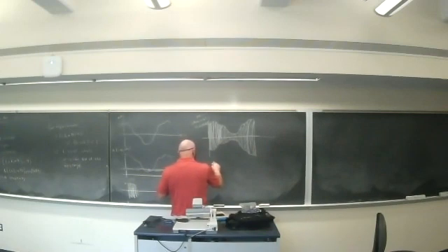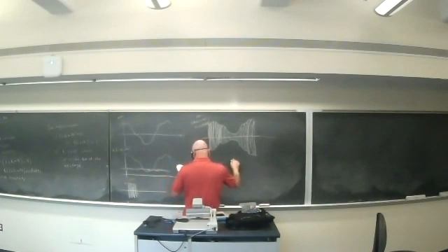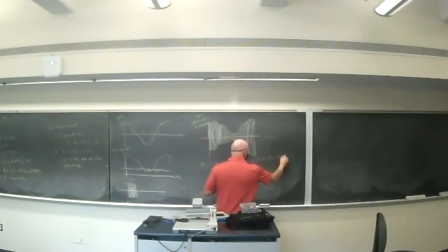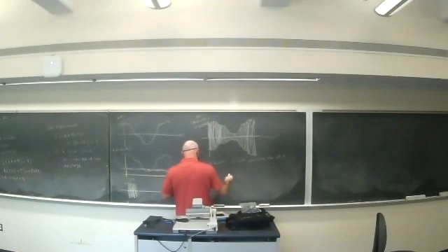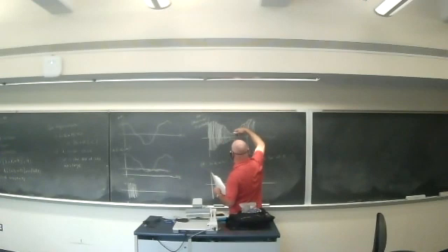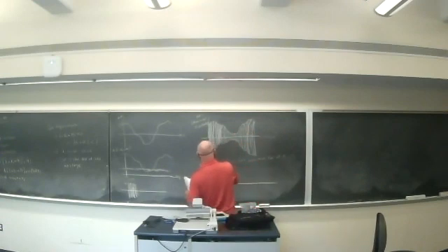if 1 plus Ka m(t) is not positive for all t, we have what's called envelope distortion. Okay, so in that case, at the very peaks here, actually at this minimum, this will actually go below 0. What that would kind of look like now would be this.